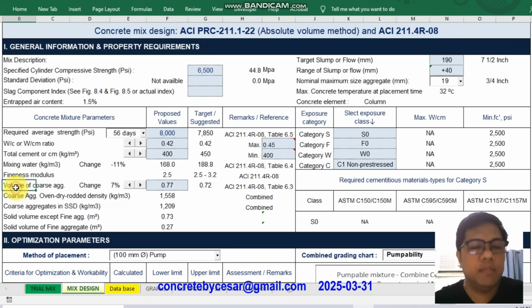For example, the paste plus air over aggregate voids is 110% for the pumpability, but the mortar fraction by volume is 55.4. The lower limit is 55 and the maximum is 57, so it is satisfactory. For the fine sand, 25%. The lower limit is 25, and for the coarse sand, 23.3, higher than the 15% lower value.